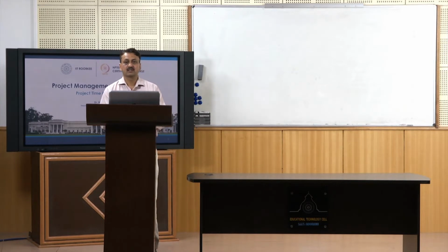There are 2 types of network techniques, CPM and PERT. CPM is a technique wherein the duration of the activity is fixed, or deterministic, or known a priori, before you start your activity, while PERT is a network where you have probabilistic time estimates.